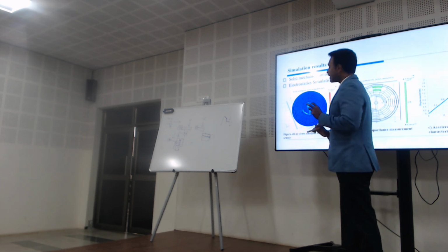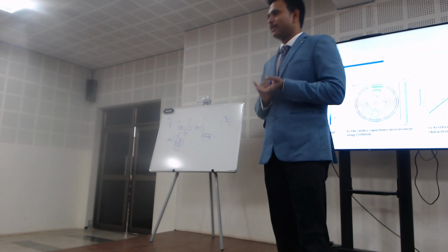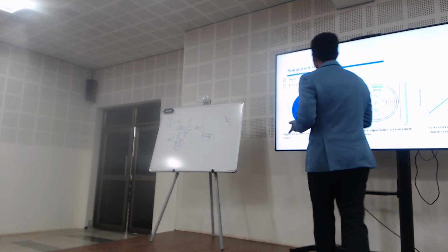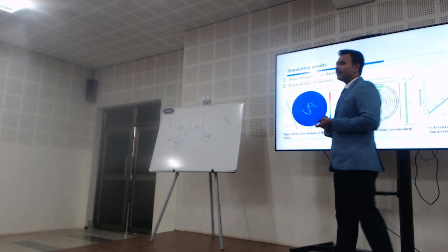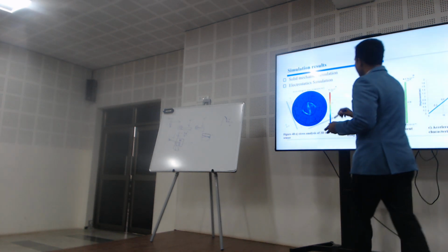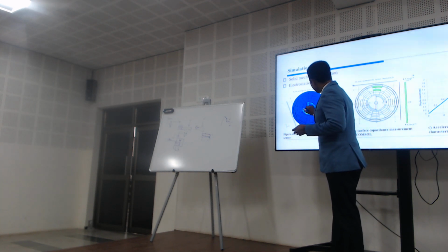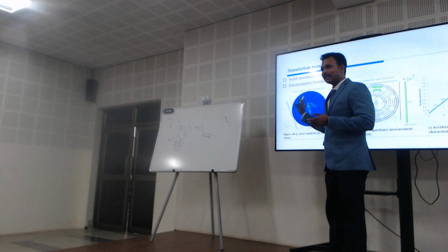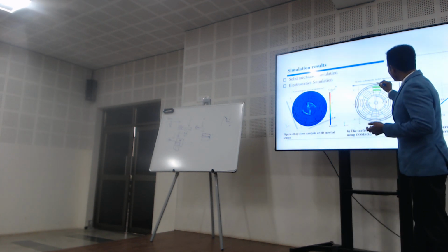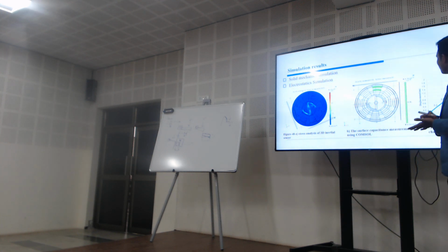First one is solid mechanics. There we can measure the stress and displacement. And the next one is the electrostatic displacements. There we can measure the capacitance. And for this structure, this is my stress analysis. Then this is the value of capacitance. So how much capacitance are we getting? That is 8.78 some femtofarads.